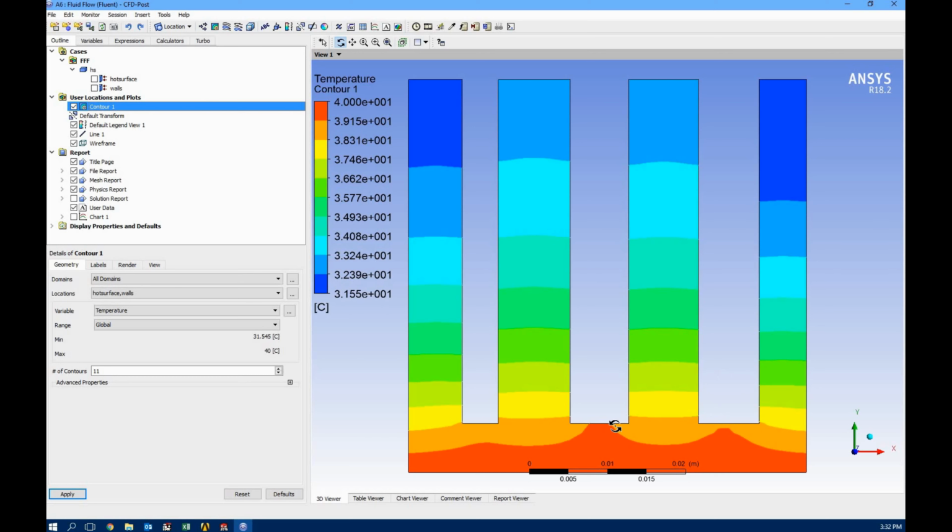and here, because this surface or bottom is closer to the hot surface, and between these gaps between the fins we have air with convection, which we decided to have a 500 convective coefficient, so they are going to cool down here, but depends on the material we have. This is aluminum, so temperature gradient is going to be, if you select copper, you are going to have different temperature contour, and it is going to be very interesting to investigate.